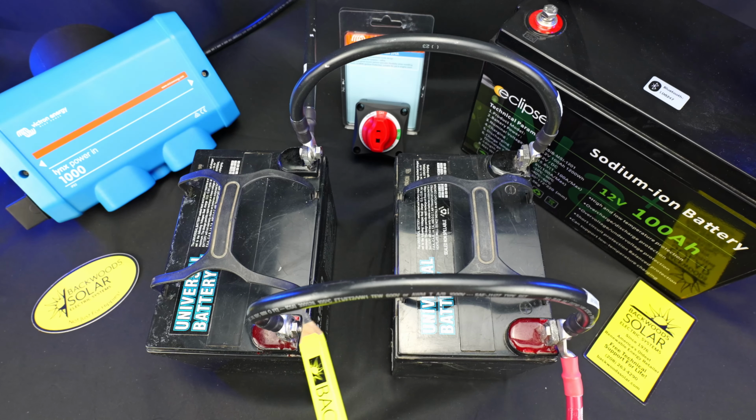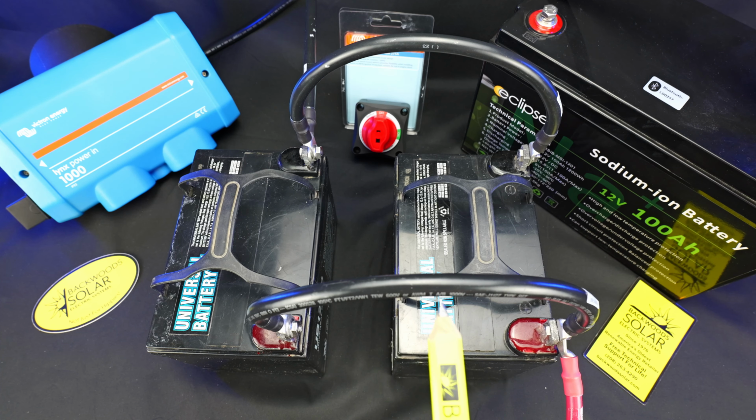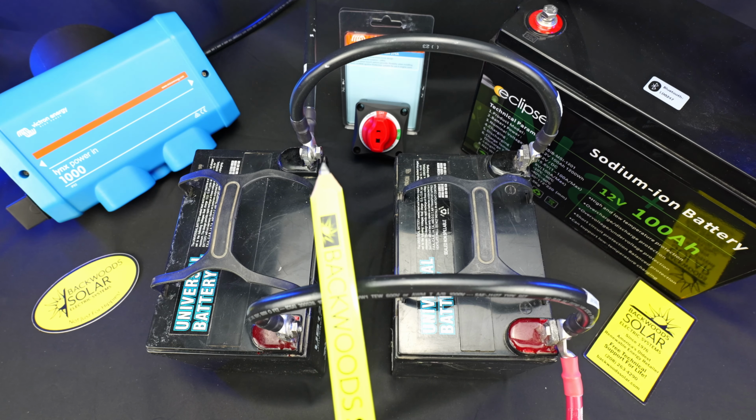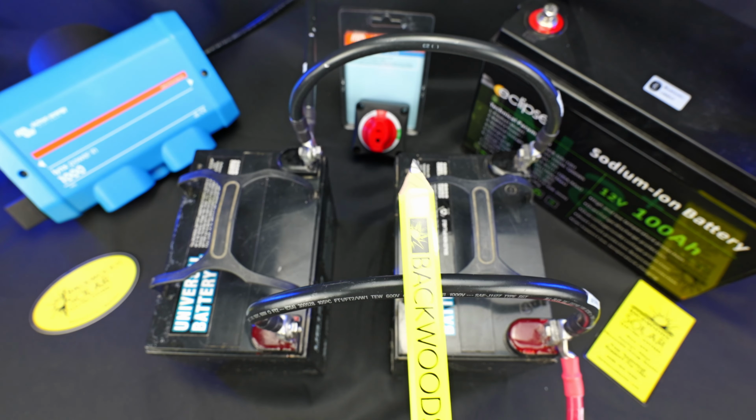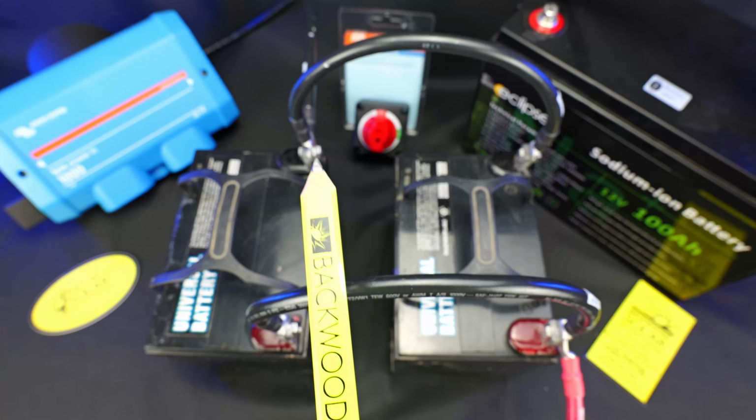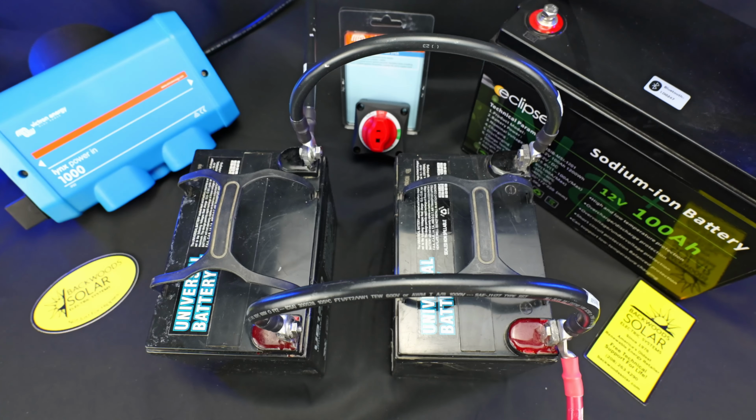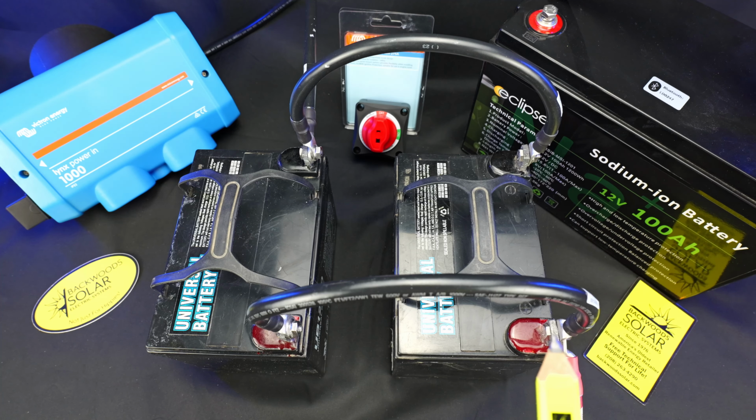If we tend to land our main system connections off of our primary battery, we tend to get uneven utilization, or there's unequal work done throughout the bank in terms of energy in, energy out. So one of the most important things when wiring, besides the overall configuration, is making sure we leave opposite corners, as you see here in this small demo.